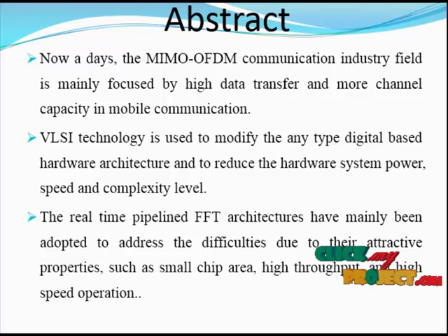An efficient combined single path delay commutator and feedback Radix-2 pipeline fast Fourier transform architecture, which includes log2 N-1 SDC stages and 1 SDF stage. The SDC processing engine is proposed to achieve 100% hardware resource utilization by sharing the common arithmetic resources in a time multiplexed approach, including both adders and multipliers. Thus, the required number of complex multipliers is reduced to log4 N-0.5 compared with log2 N-1 for the other Radix-2 SDC SDF architectures.